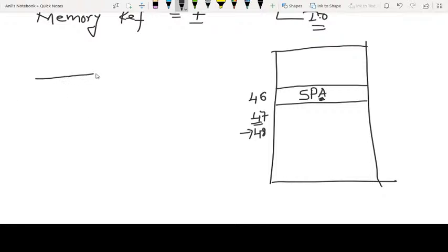You know the accumulator register. The accumulator is a 16-bit register, bits 0 to 15, in which the most significant digit, the 15th, is what you call the sign digit. If it is 0, it is positive; if it is 1, it is negative. In order to identify whether the contents of the accumulator are positive or negative, we need to check the most significant digit. Checking one digit in the accumulator will always be difficult. Rather than coming to the accumulator and checking it, we will directly check the flag register.